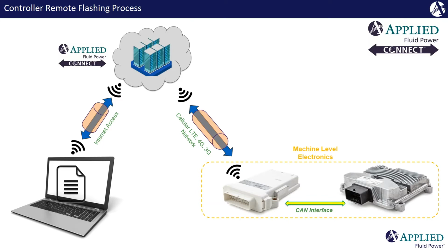So now what you're going to need is an update file. Depending on the controller, this could be an update package, or it can just be an APP or hex file that comes from a programmer's laptop. Now it's important to note it doesn't need to be the programmer that does this. This could be something that one of your technical support people does for you. But either way, start with that file.